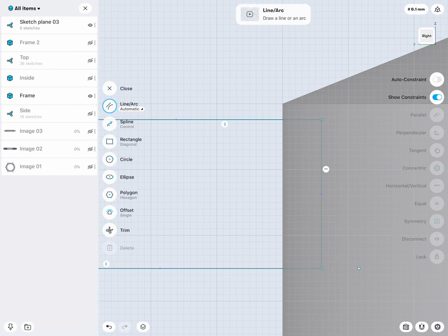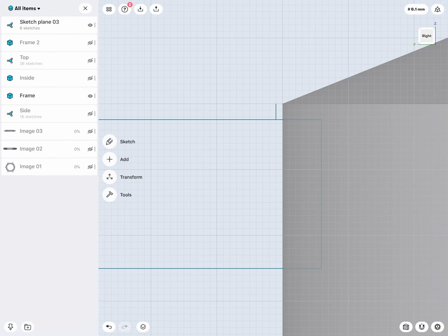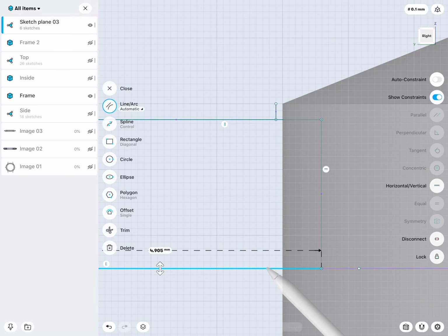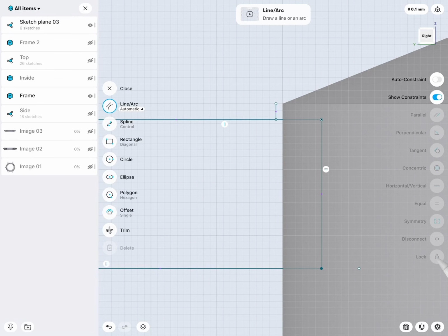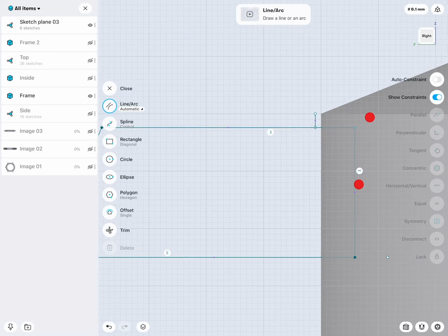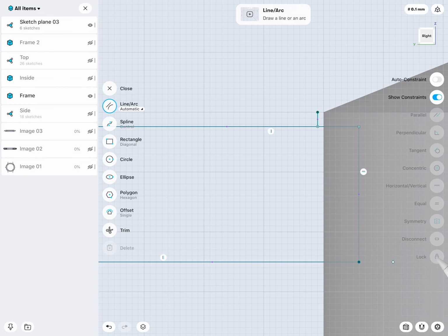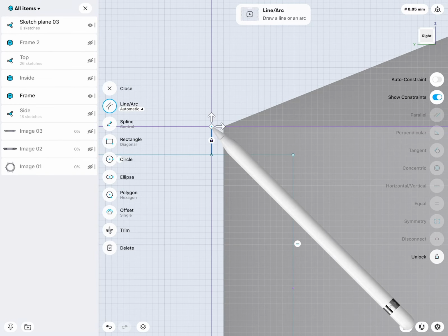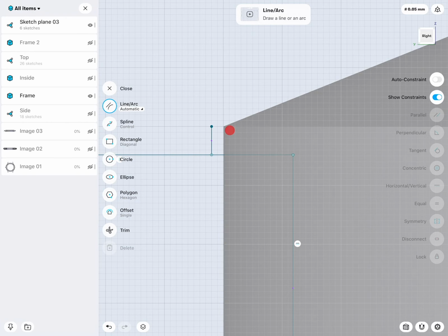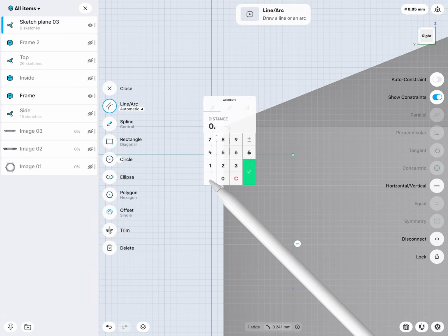So now this line is centered as an axis. Also, what's the distance here? So 2.4. Let's say we want this to be 2.5. Check this out. So I will lock the axis. Then I will lock the starting point. You see the starting point lines up with this sharp corner. I want this to be vertical. Now I can go ahead and say 0.25.